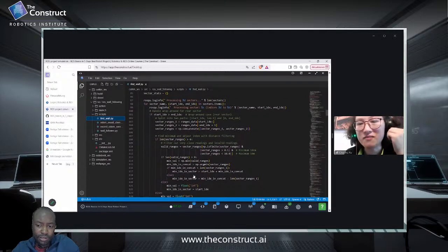It doesn't differ from anything. All the obstacles are recognized as wall, actually. So it reads from the laser beam which sector of the beam. The sector is 15 degrees, and I average the detection. If one of the sectors has detected the minimum distance to any obstacle, then this sector defines the angle to turn to when the robot rotates to face the wall.